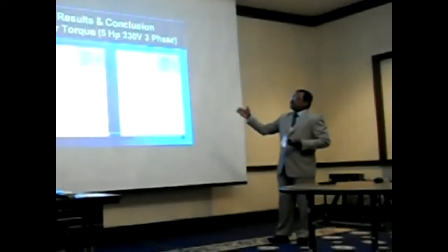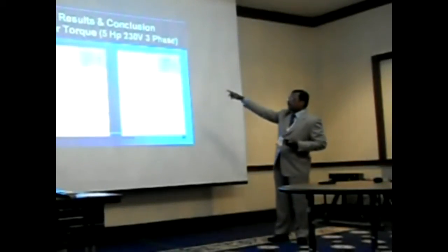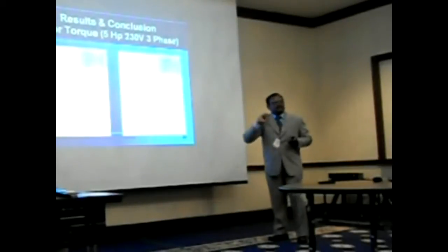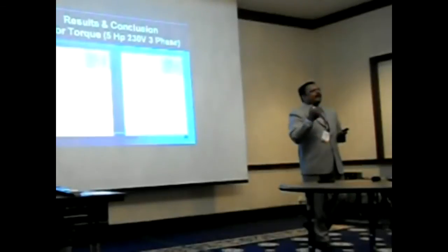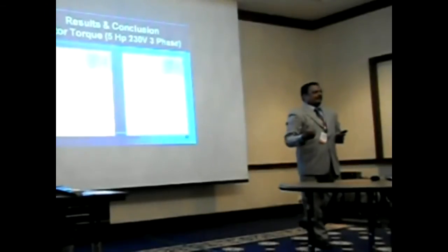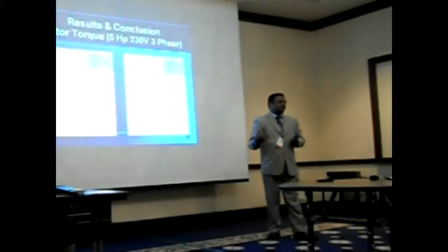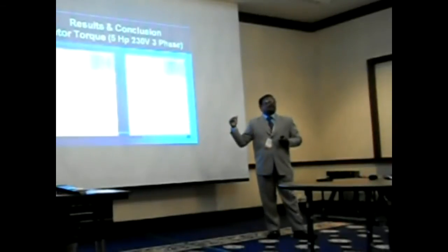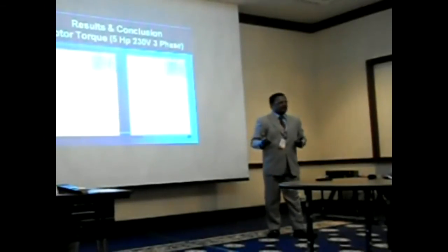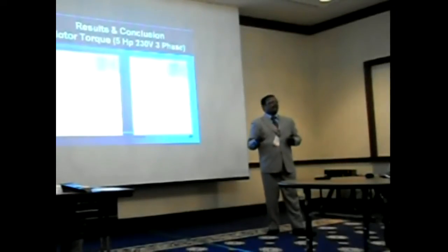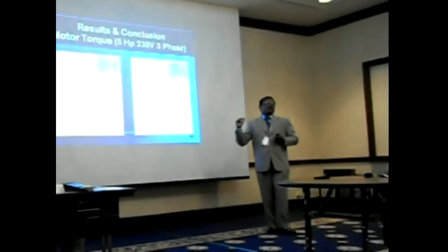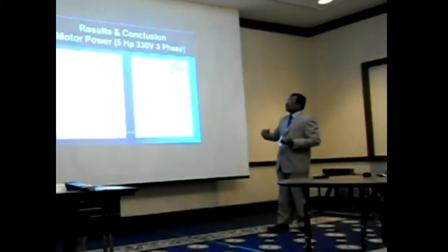Similarly, the torque developed is slightly less, but the starting torque goes into making the armature rotate from a stationary condition rather than pulling the load. So having a reduced torque at that stage is not going to affect your loading conditions, because the armature is stationary and not actually pulling any load. So this reduces the losses at the starting stage.